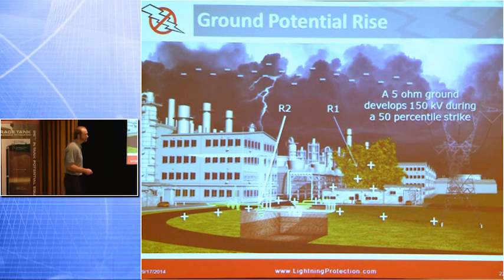We'll see this quite often in a chemical plant, power plant environment, where you'll have maybe the DCS because Foxboro or Bailey Controls says, hey, I could have my instrument grade ground and I want it completely isolated because I'm so sensitive, I don't want any noise on there. And then you have the plant ground. So the plant ground can be described basically as R1 and R2 is your DCS ground. So they're totally isolated from each other. They're both ground rods in the earth, but the plant ground is a significant large ground. It's the whole plant ground. It's all tied together. It's structural steel, it's the vessels, it's the foundation, it's the electrical system all tied together. Well, this DCS is out here with 3 8-foot rods in a triad by themselves. They're not tied to the grid.